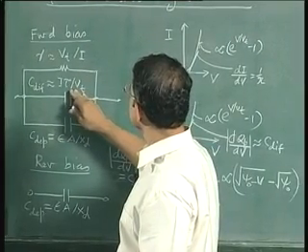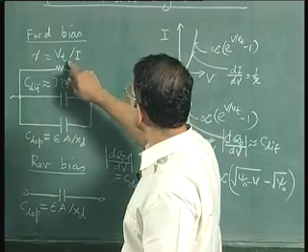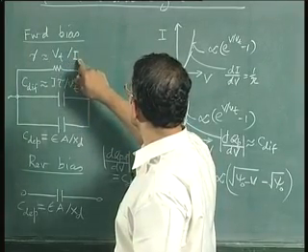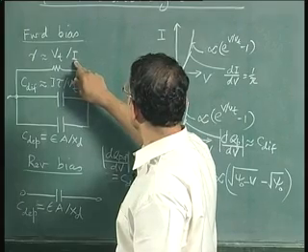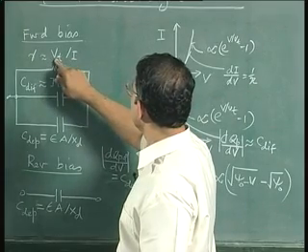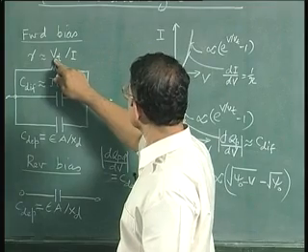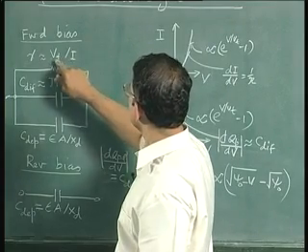Now what about the resistance, the small signal resistance? The small signal resistance, as you can see, if the currents are in the milliampere range, since Vt at room temperature is of the order of 25 or 26 millivolts, this is of the order of ohms.